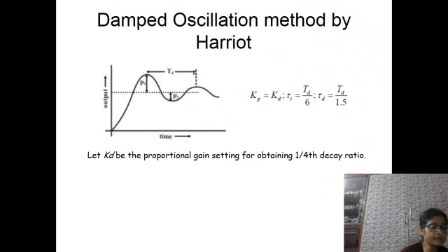The value of the gain is taken as the optimal value of the proportional mode of a PID controller, and for the integral and derivative action, using a certain mathematical model from these experimental values, the parameter values are obtained for the PID controller.